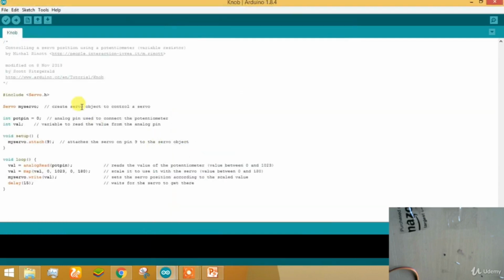Here you can see that the default library of the servo motor is called, the library is given an object, and the object is selected for all the operations. Here the object is said that the servo motor is attached at pin number 9 of the Arduino board. The pin number 9 will be giving the pulse width modulation signal for the servo motor to rotate.